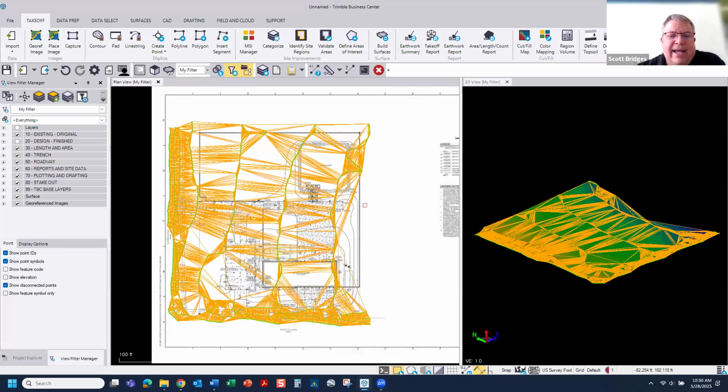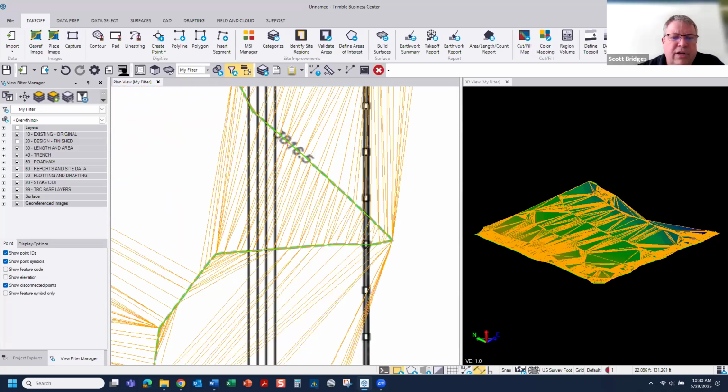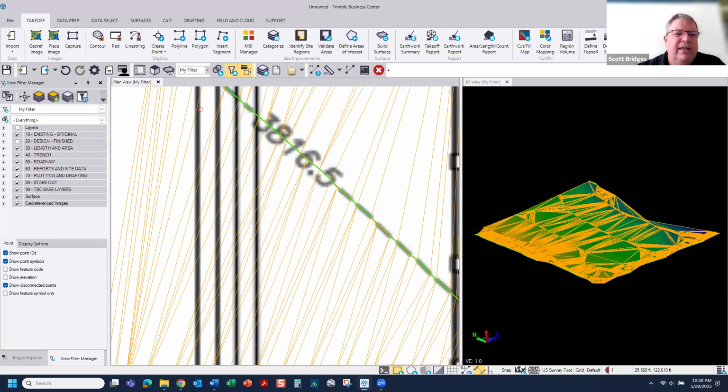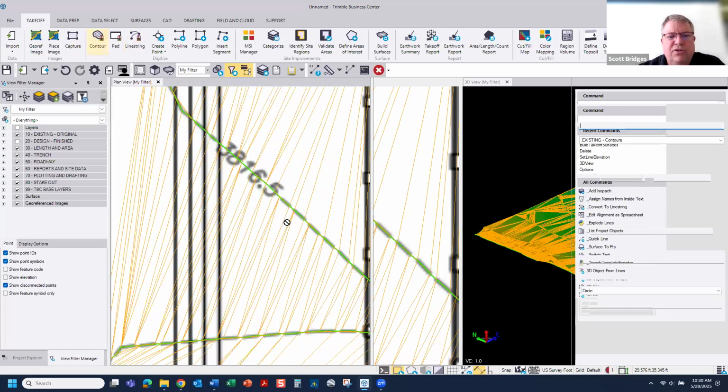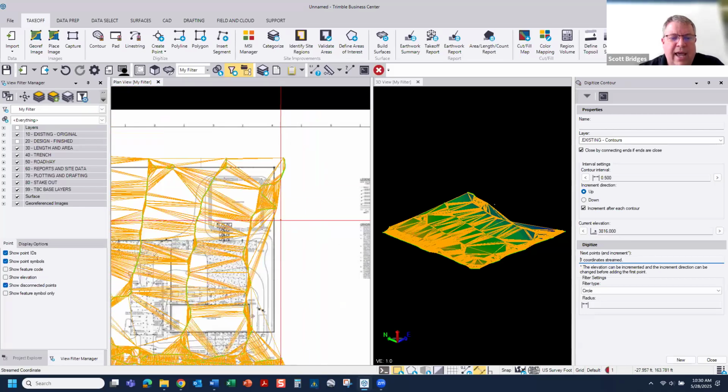So by looking at that, I can tell I probably need one more line over here, one more contour. So you can look at the information and say, okay, let's add one manually. Let's go through Takeoff and add a contour. We'll use 3816. This is just a judgment call. You would take a look and we would want to drop this number down. So here I can drop it down to 3816. I activate where I want to digitize it and I can just select one more spot.